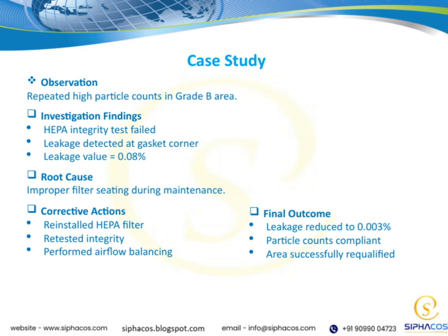To correct this, we reinstalled the HEPA filter properly, then performed another integrity test to ensure it was sealed correctly. Additionally, we balanced the airflow across the system to prevent future issues and maintain consistent environmental conditions. These corrective actions not only resolved the immediate problem, but also reinforced the importance of proper maintenance procedures. This case underscores how critical attention to detail and thorough testing are in maintaining a clean and compliant environment.